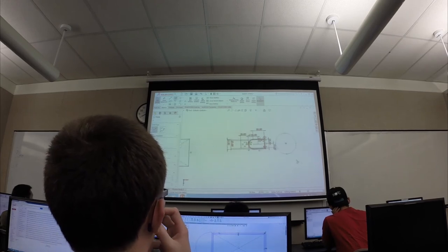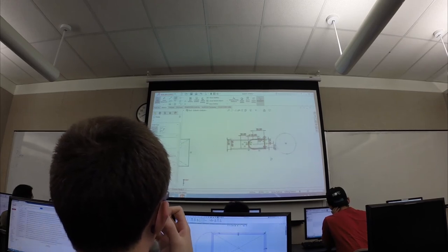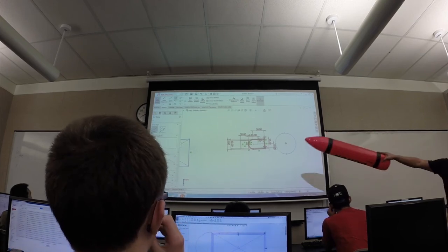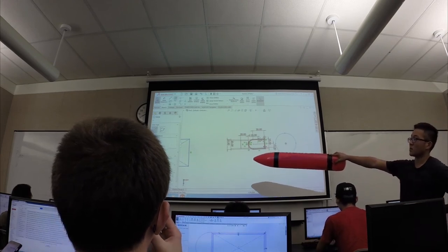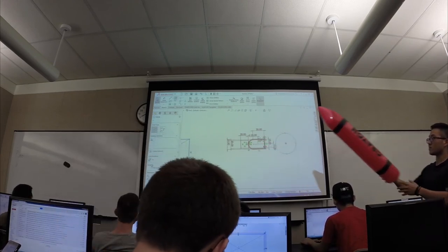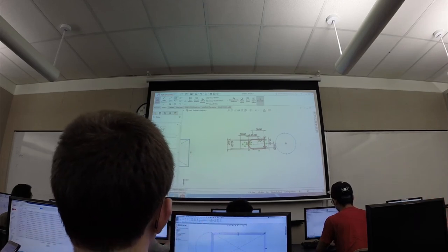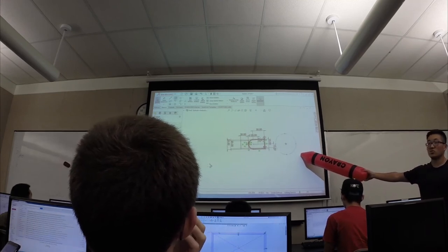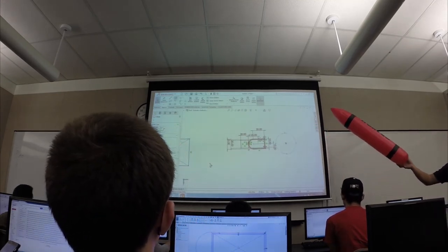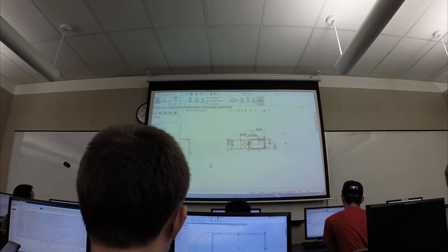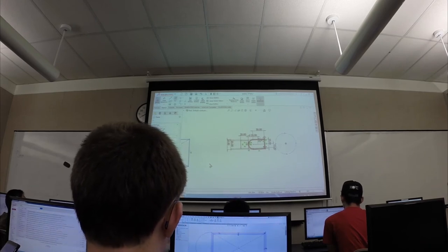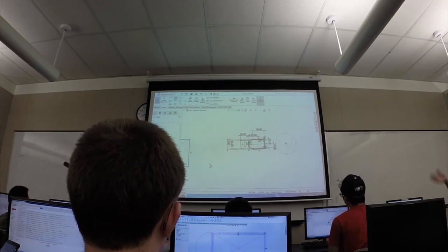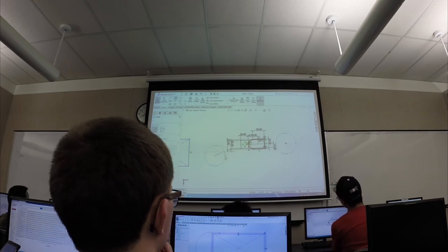And we're just going to draw a circle. So currently the circle is selected after you drew it. And then right here in your properties manager, under options, there's a little checkbox that says For Construction. As soon as you click the For Construction box, you'll notice that your solid blue circle turned into a dotted blue circle, right? So now that sketch is not a boundary sketch. The software doesn't treat it as a limit to a sketch. It is purely there for reference reasons, and we'll show why we need that.